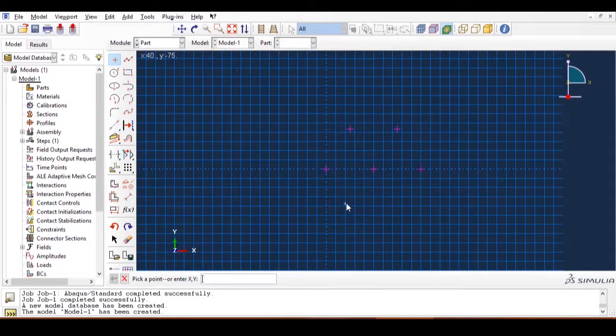So how are we giving these points? We know our truss is made up of a 100 mm span and it is an equilateral triangle. So it is going to be a 100 mm equilateral triangle. We are going to find out the height from the trigonometric ratio. It is going to be around 86.6, which is roughly 87. And from this we are going to formulate two equilateral triangles to form the truss.